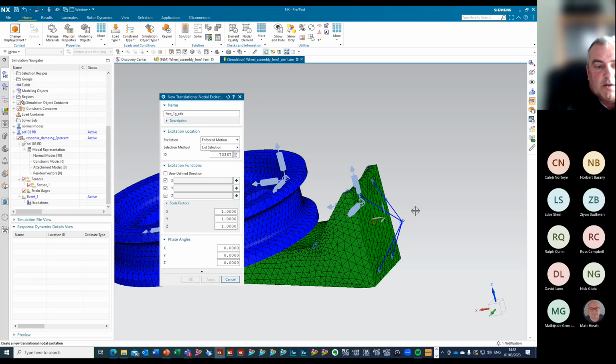It just makes that process a lot easier. In this input, it probably isn't going to make much difference, but if I was doing random, it would, because if I tried to put the random into all four holes, I would then have to phase them all together. Because it's a random spectra, I wouldn't necessarily be putting the same input into every one of the holes, so I'd need to cross-correlate them to get the right value. Whereas if I've only got one point and I put a random input in, then all four holes are fully in phase and using the same input. That's why we tend to do it this way. It, again, just makes it a bit easier. So here we're going to do it in Z.